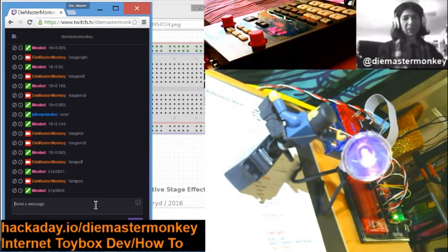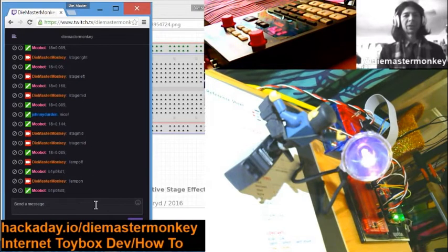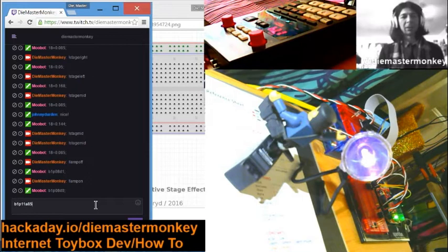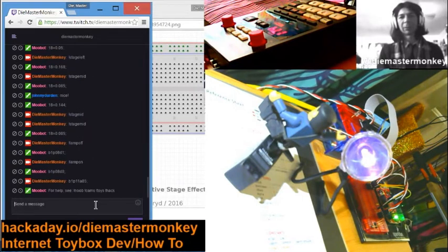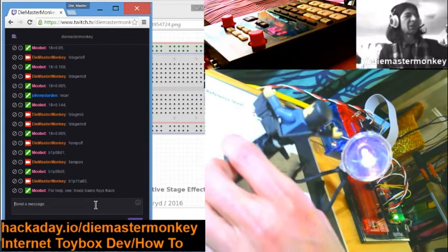Okay, so I think that worked out pretty well. In only 30 minutes, we've already gotten a servo working. It's already set up. We can simply control it. What was it? It's B1P11A, and then a number generally between, well, it depends. We can get into that later, but 85 will probably work. See, and then Spock moves to the 85 position.